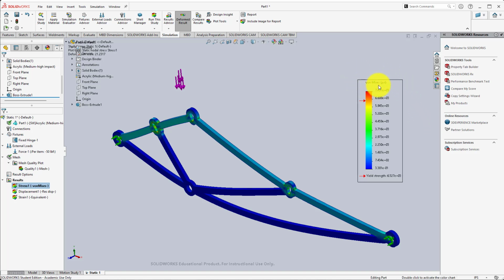Von Mises stress. What is von Mises? In a short definition, it's combined stresses. So things like shear, bending, torsion stresses, we're combining those as one common stress. So we can sum the squares and square root it and get that kind of result.